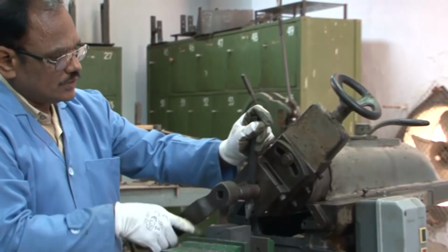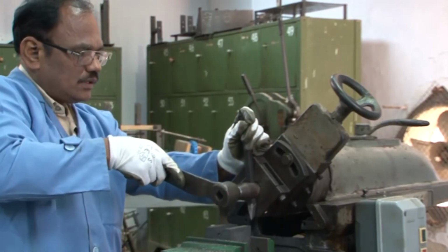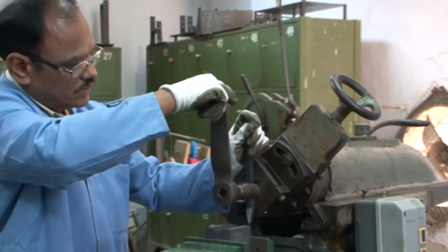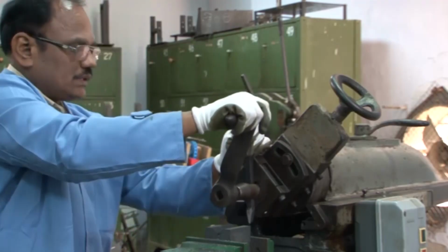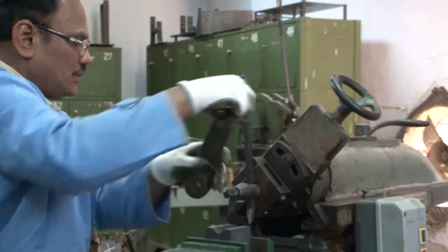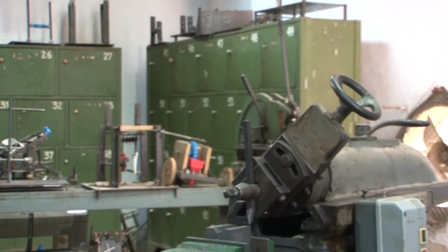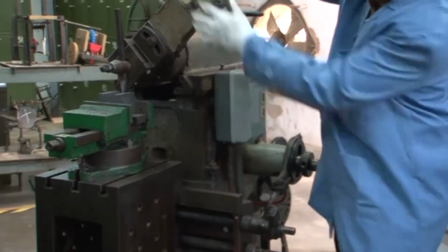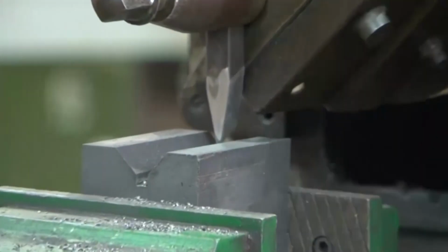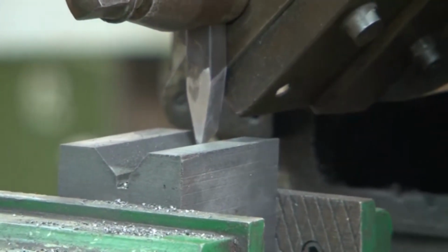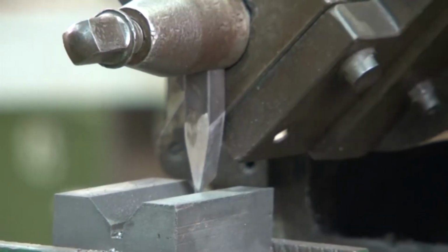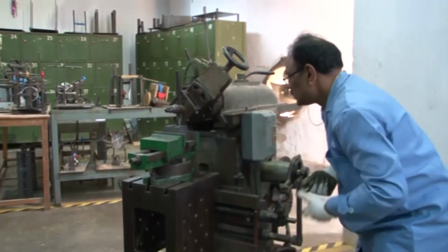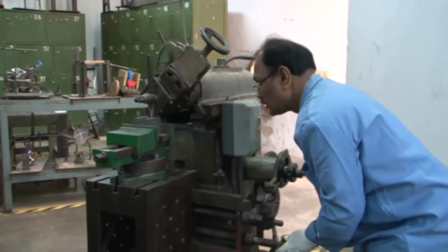Now, the tool is straightened up. See, the tool post has been inclined, as you can see, and the tool has to be straightened up, because tool cannot cut, as you understand, at that angle of 45 degrees. So, tool has to be exactly straight, that has to be made with the head inclined at an angle of 45 degree once again. And once again the same operation will be conducted, that is the tool has to be in touch with the workpiece initially, then the depth of cut will be given, and step by step the operation will be completed for the inclined surface of the dovetail. So, at this moment we are preparing actually the left side of the piece.